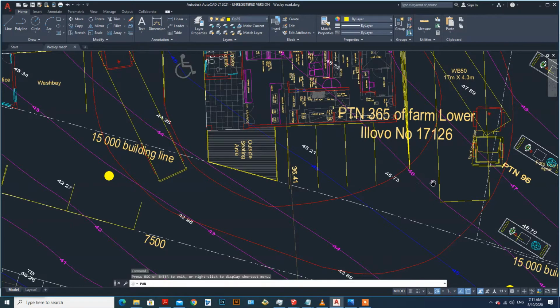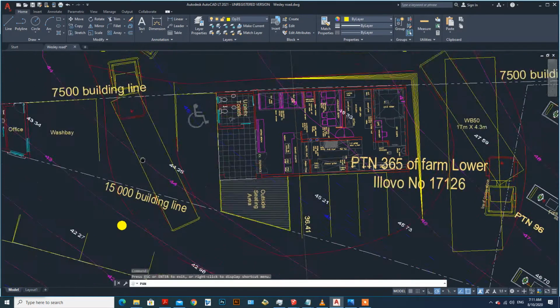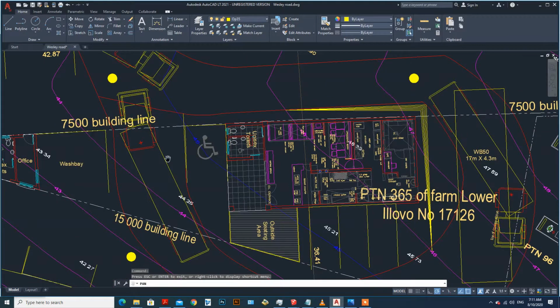Although the proposed slope of this parking should be 1:15, I'm still concerned. Looking at the condos here, condo number 48 and 43 have a difference of about 4 meters within this section, so this drive is going to be quite steep. On the exit side, this part of the road is also quite steep where it joins the origin. We are probably going to extend these walls here and form another angle. We're going to cave it and put up another retaining wall here. This side here will still need another retaining wall.